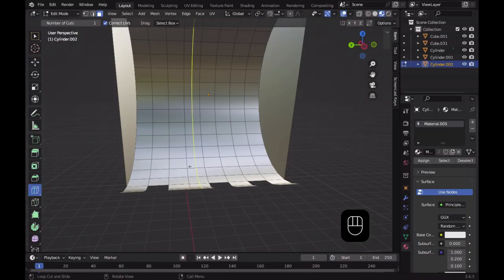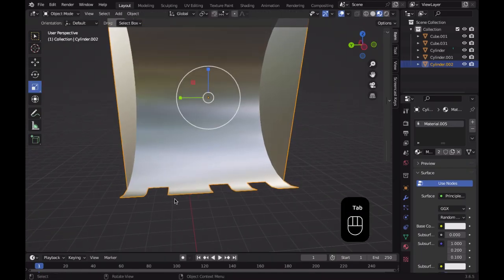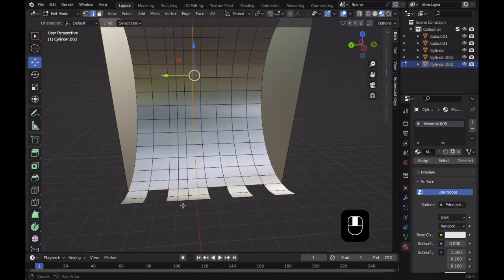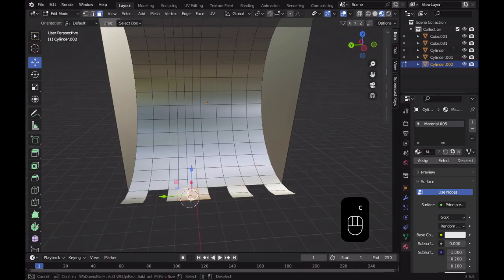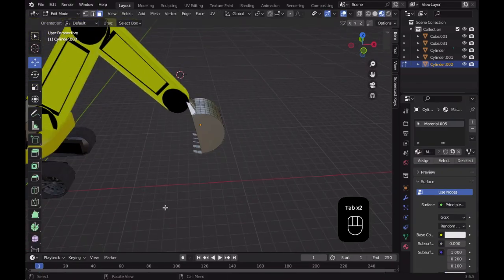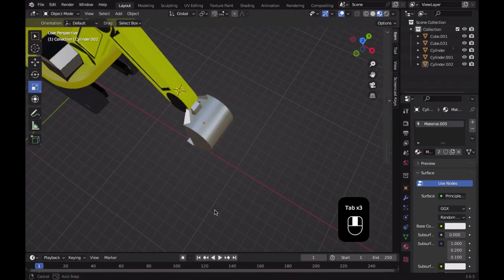Click on this loop cut and this one, and then we're going to click that out of that, click on the faces, click on that, and then we're going to click on this one here, these four, not the edges, we want the faces. So this and just this. So actually click off it in case it clicks something else. Then press X to delete faces, just like this. So yeah, it doesn't have to look too exact, of course.